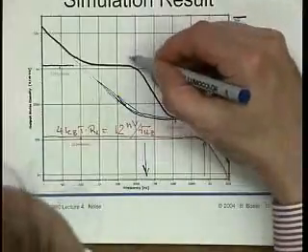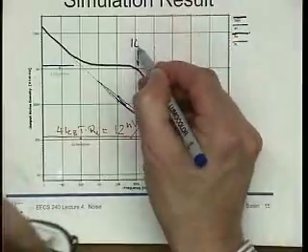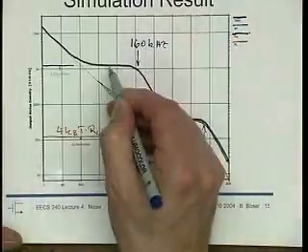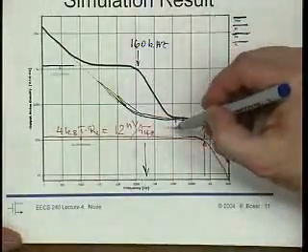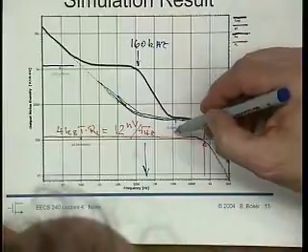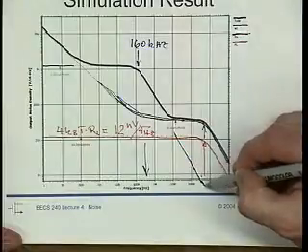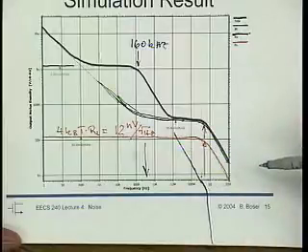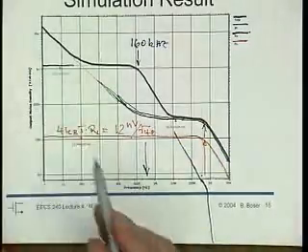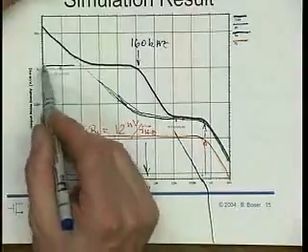And then we would expect here that at 160 kilohertz, we'd expect this to roll off, and lo and behold, it does. And here it's absolutely the dominant noise source, and then it keeps rolling off, and of course here we're going to see a second pole, but it's no longer plotted on my graph. So it actually would go on like this. Right? It doesn't have flicker noise, the resistor. In principle, resistors can have flicker noise, but usually negligible, unless they're particularly bad. And so it goes flat here.